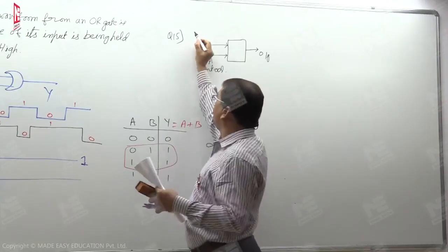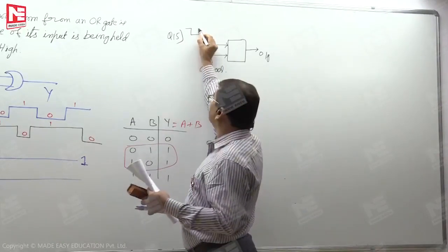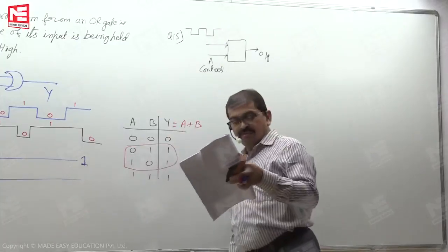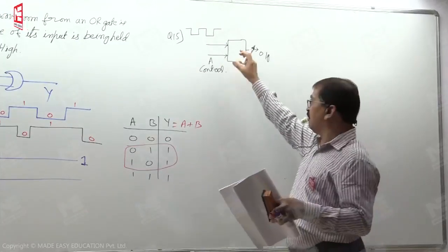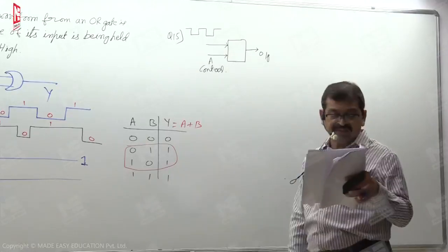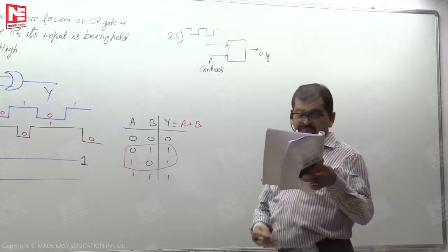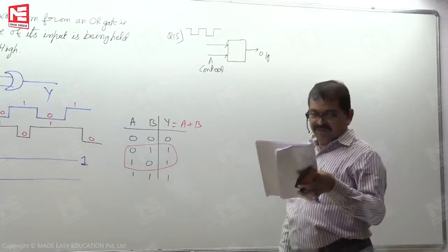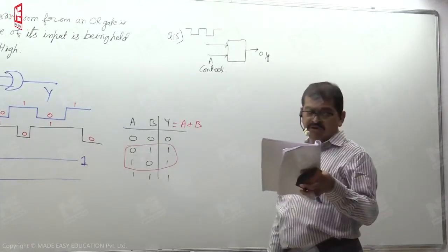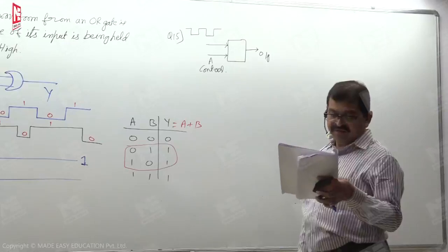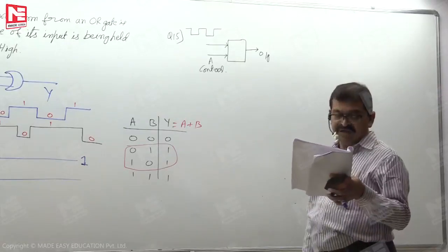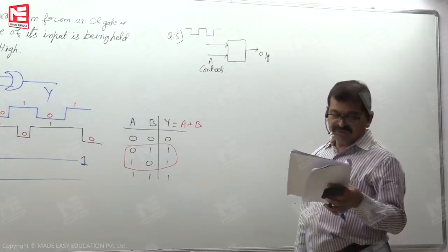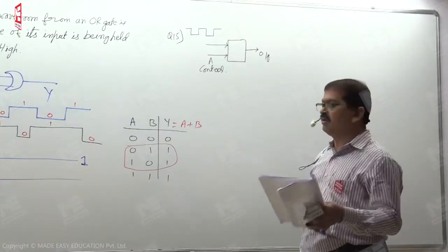We are looking at the A input with a waveform like this. Now the question is, what is the box we have here? The black box inverts the phase of its input V when control input A is 1, and lets it pass through uninverted when control input A is 0. The circuit is the question.